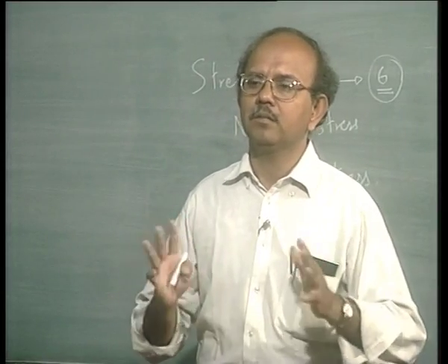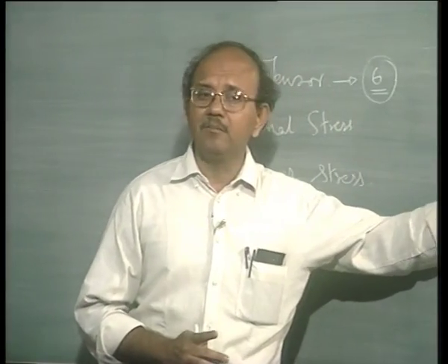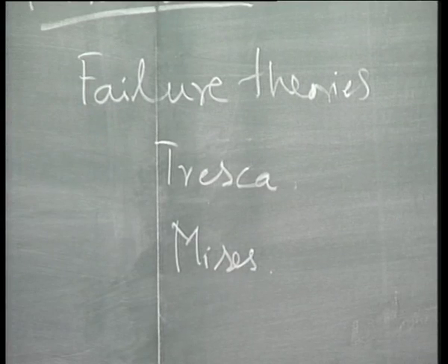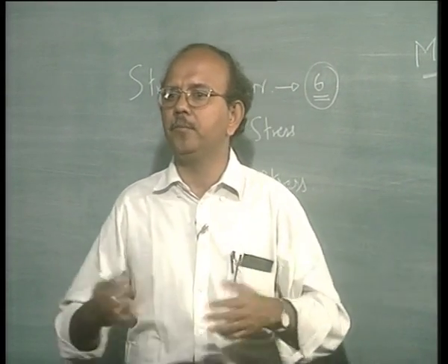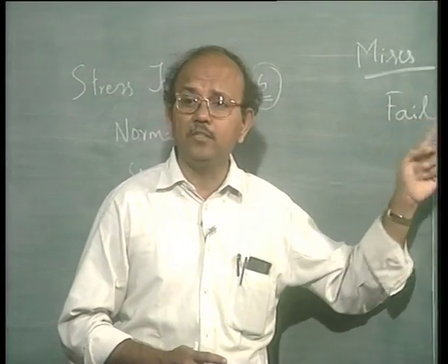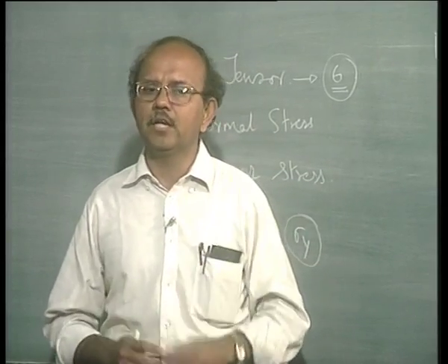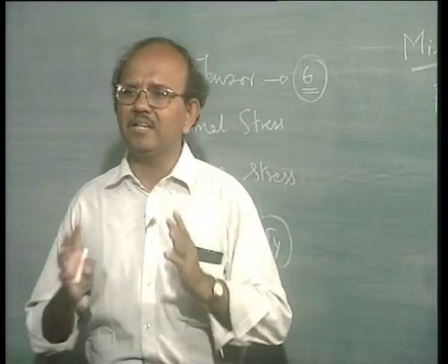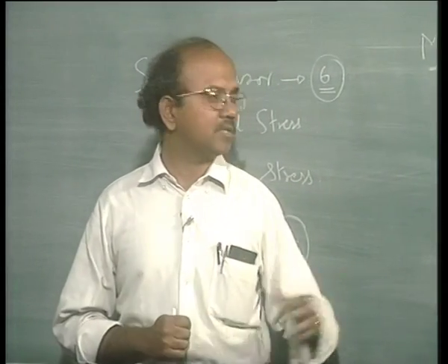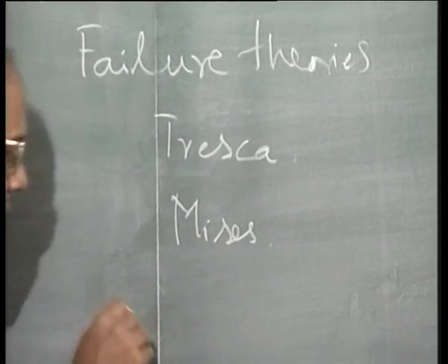This is what was first thought about, and hence failure means not fracture, but failure to do the intended purpose. That is what is meant by failure theories. It failed to do the intended purpose for which you designed the component, and hence people started calling these failure theories. But the current terminology today is not failure theory; they are called yield theories.